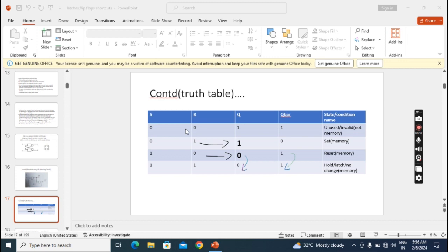We can apply any of these combinations, because even though we don't know the second input and there is no output to feedback, in these three combinations at least one of the inputs is 0, and in a NAND gate, if one of the inputs is 0, the output will become 1. Like that we can get the output. So we can apply any of these three combinations.